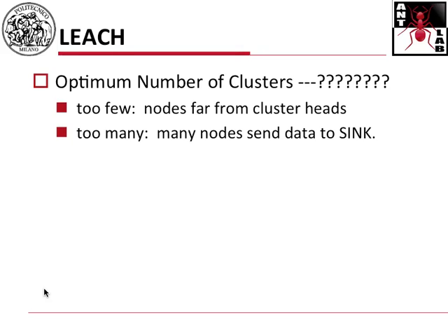The drawback is basically if you force your network to have very few clusters, most likely the non-clustered nodes will be far away from the cluster head, which means that they may have worse link quality because they are farther away. Or conversely, they need to transmit with more power to reach the cluster head.